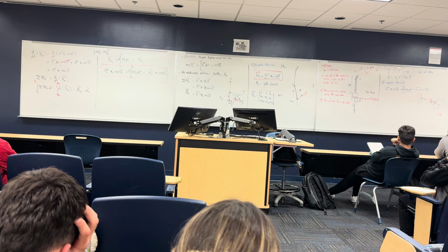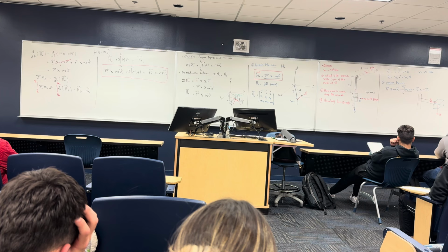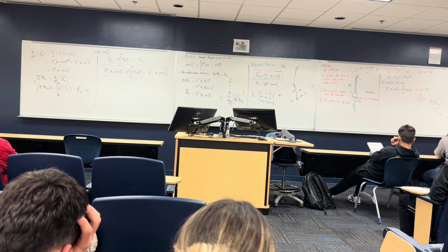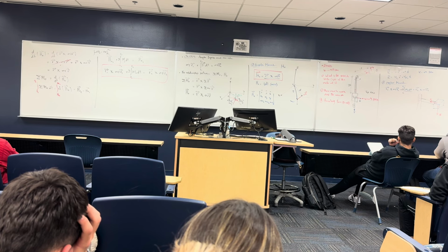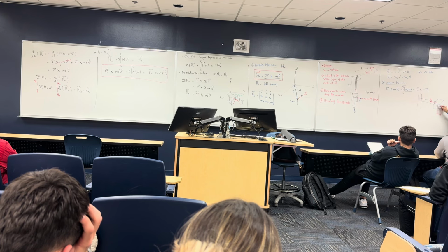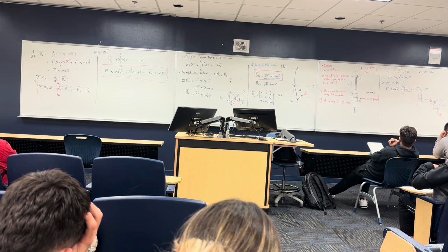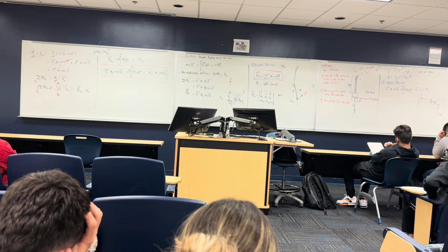And we have something like this. This arm is going this way. So the force is passing through this line, right? It's not gonna make a moment, because it doesn't have any arm. The weight is going down. It doesn't make any moment because the line that I'm getting the moment about is parallel to the force. When you're gonna have a moment is when your force acts this way. This is gonna make a moment like this. That's why this is gonna rotate, right? So this is the only way. But the weight is not making any moment about this line.